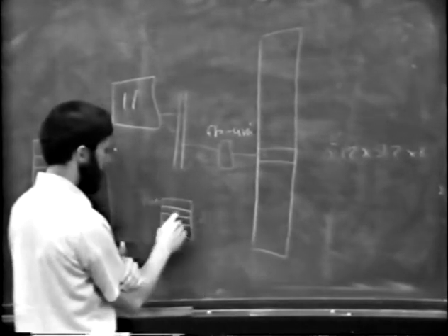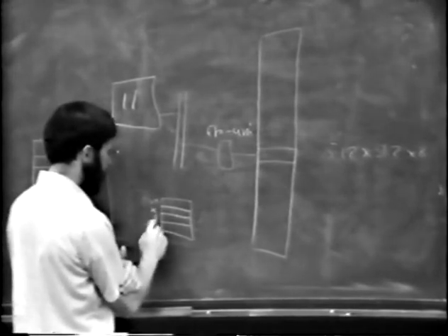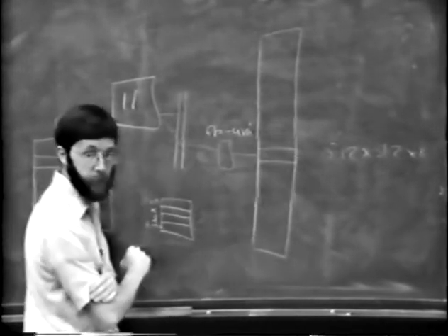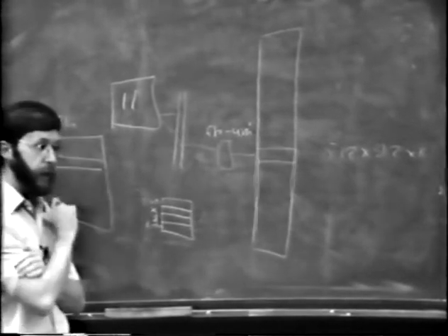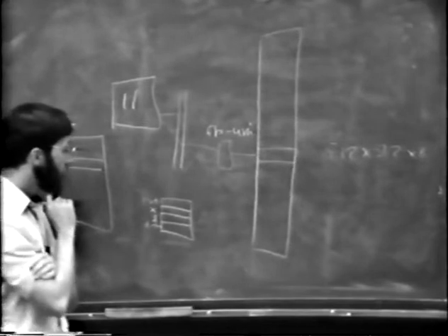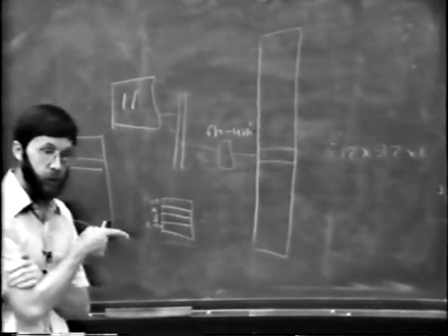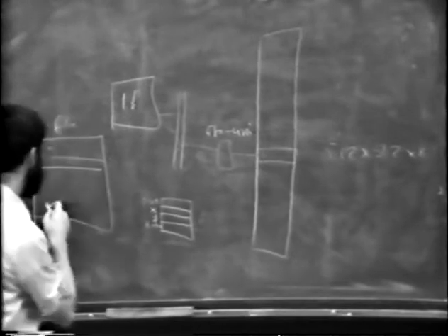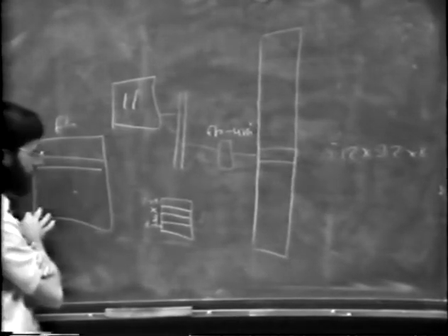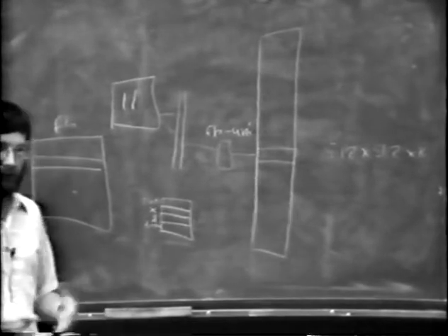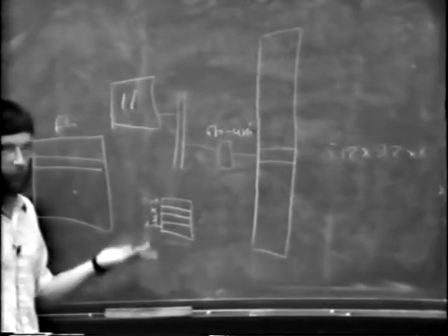I'll explain that in a minute. The second one is X, third is Y, and the last one is data. So you could write in an X and a Y, and then you could read or write a byte or a word, and it would come from the right place in the memory. So you set any XY you want, and then you could just read the pixel, which is typically what happened, and that's it. It's read in the register.